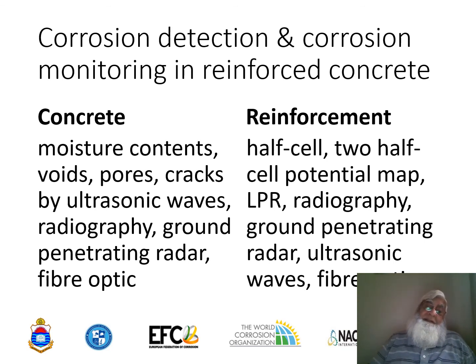Another thing is, if you want to know at what rate the concrete-embedded reinforcement is likely to corrode, then we can use a technique called LPR, linear polarization resistance, which can measure the corrosion of the reinforcement, provided the instrument and electrode are the same material as the reinforcement.